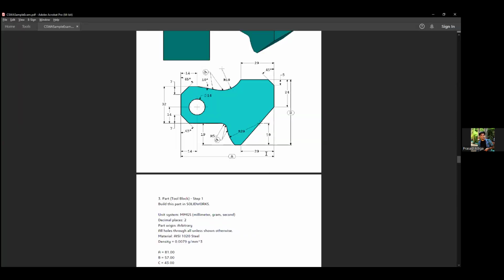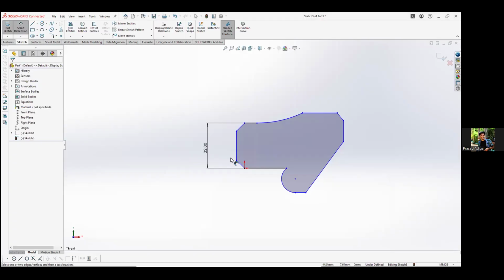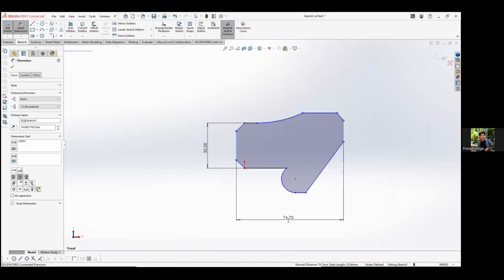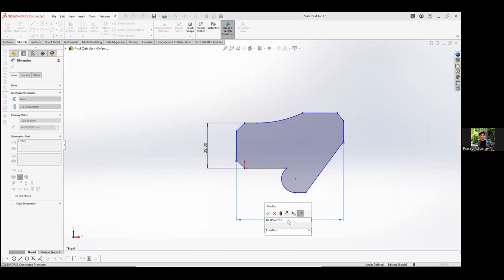And how do we give this A? Since A is a variable, we have to set it as a global equation. How do we do that? Just select these two lines, and when you're entering the variable, select the equal sign and then type A. Now when you click on this, it assigns this value to the equation A.